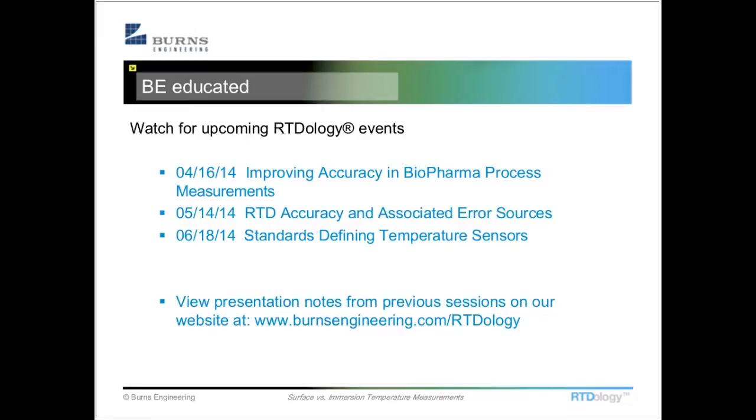I've seen a lot of applications like that where an 1/8" diameter sensor with maybe 1 1/4" of immersion seems to work real well. And if you can get a little more immersion, that's even better. Putting it into a sanitary tee, for example, so you can get even more immersion, is another good solution.